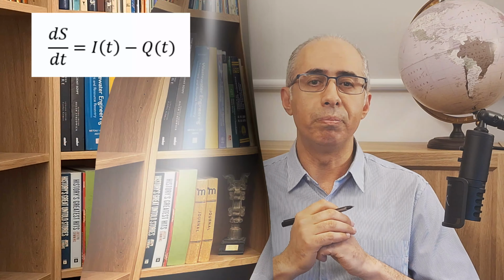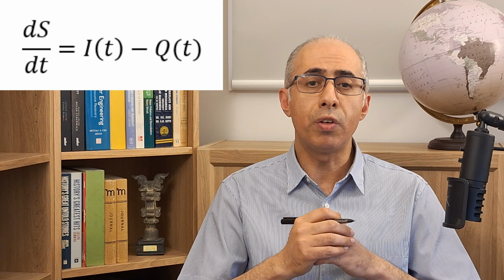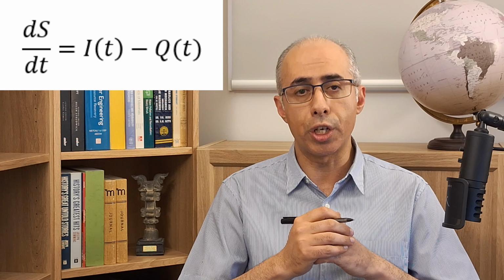The heart of RORB's channel routing system is the Laurenson nonlinear storage method. To explain this, we need to refer to the foundation of any hydrological routing system, the continuity equation. dS/dt, the change in storage over time, is equal to inflow I minus outflow Q. To solve this, a second relationship is required. In the Laurenson method used by RORB, this equation is conceptualized by assuming that the storage in the channel is a power function of outflow discharge.